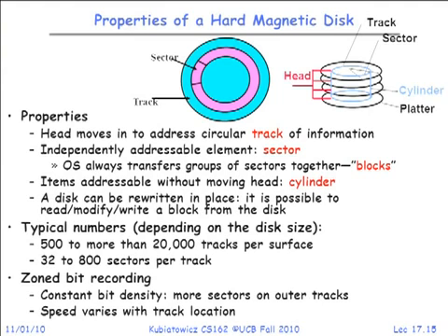That's the way they used to make disks in the old days. The problem with that is that your density varies. And if you're really trying to cram as many bits on as possible, it means you're wasting possibilities on the outside, because you've got to be able to somehow distinguish some density on the inside. So that's why what they have today is called zoned bit recording, where the density is constant and therefore you have more sectors on the outside than on the inside.